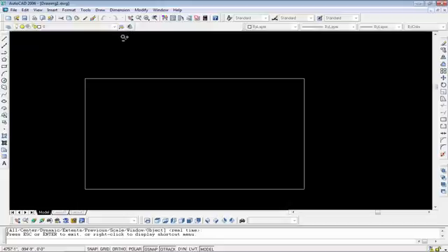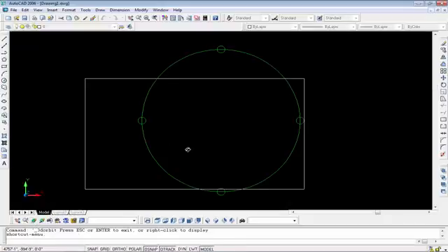When you need to zoom in 2D view, definitely you will use this one. And when you need to zoom in 3D form, in the 3D section, you will use this one. Okay, the third option is orbit, 3D orbit. This is a very awesome tool and one of my favorite tools. It is very easy to use. Just simply click on it and move.